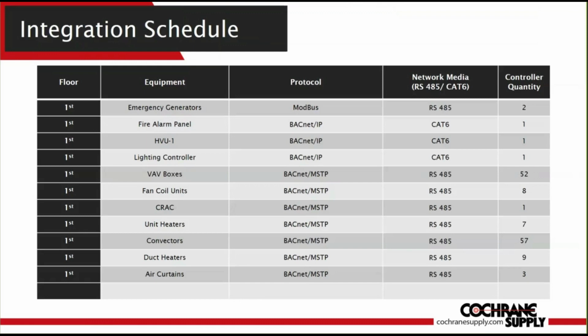So this is the type of schedule you're going to want to put together when you show your overall topology. As a consulting engineer, you don't want to show the subnetworks. You want to show a VAV box controller typical for 52, right? So you as a consulting engineer, you have to know that, okay, well, a typical VAV box or IP type of network or subnetwork, you can typically only network or daisy chain a minimum of this and a maximum of that.